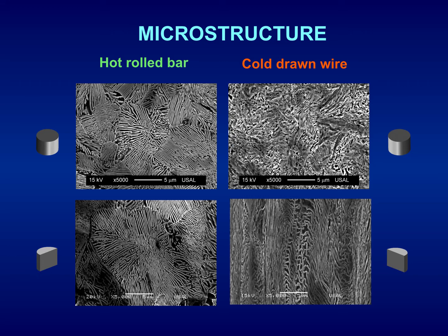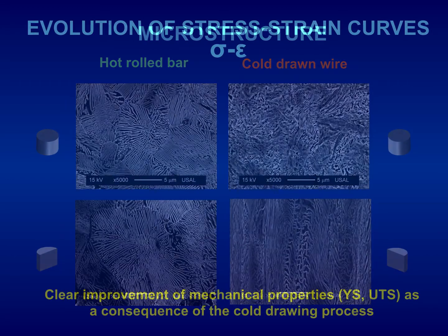While the hot rolled bar exhibits a randomly oriented pearlitic microstructure in both transverse and longitudinal direction, the fully drawn material exhibits in the transverse direction a more or less non-oriented isotropic structure with curved cementite, but in the longitudinal direction it exhibits a markedly oriented microstructure, oriented and enlarged in the y-axis or cold drawing direction.